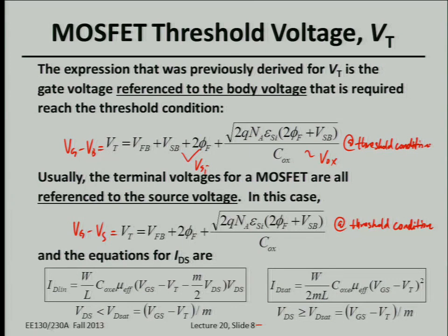Actually, we'll find that in reality, the corresponding drain current will be lower than what we approximated at the beginning, right? So that's why you need to take into account the impact of the body bias, or the impact of the depletion charge. That's why you get the drive current always reduced compared with the very simple model.